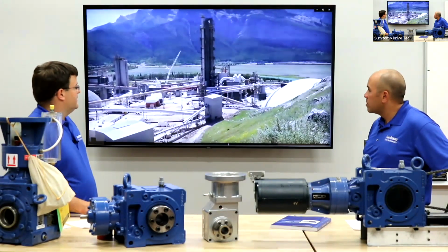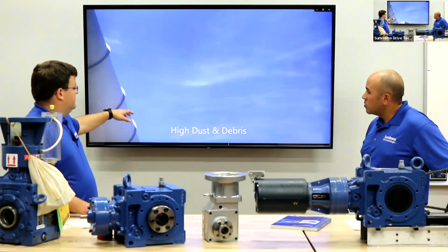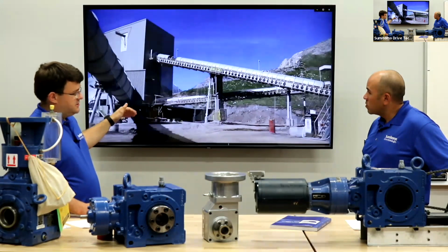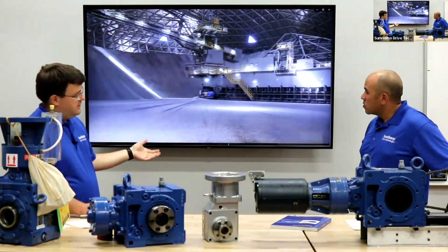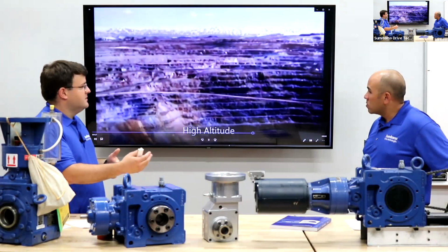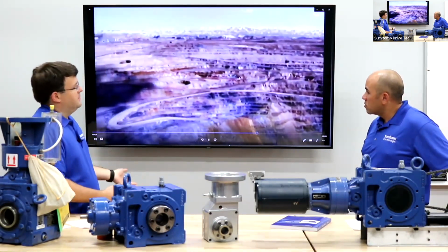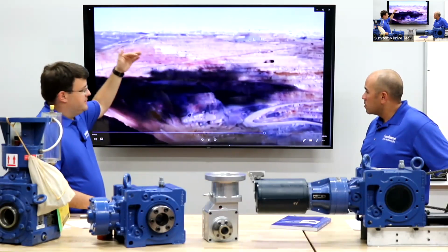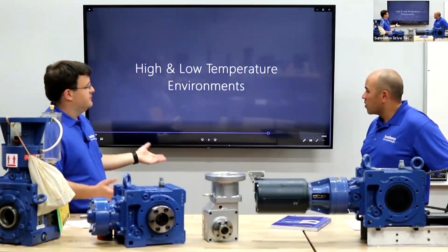Correct. Gotcha. Okay. So this one here, high altitude, high dust and high debris, mainly high altitude. This one can change your selection because at high altitude, the air is thinner. And from there, cooling isn't the same. So you need to compensate with a slightly larger box to make sure it stays cool in certain applications. So if it's running constantly, it'll run a little bit hotter at a higher altitude because the air isn't as good for gearbox cooling.